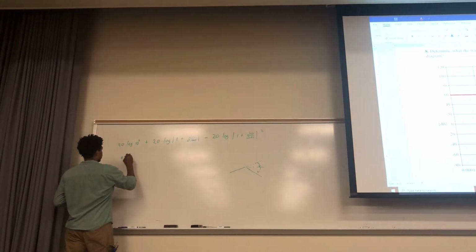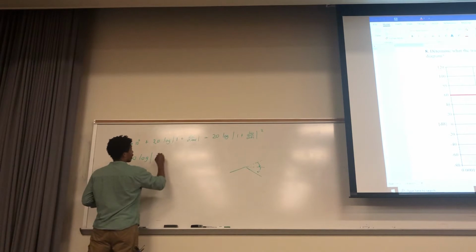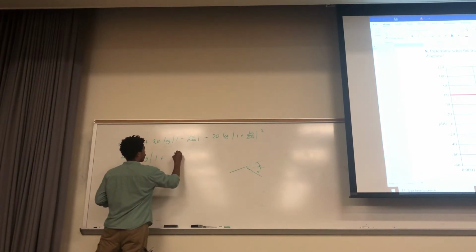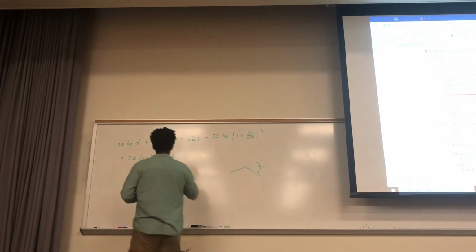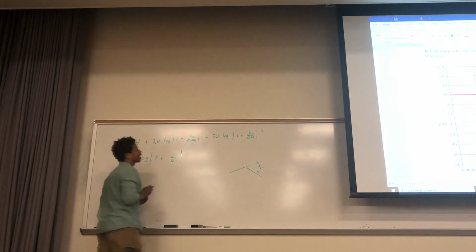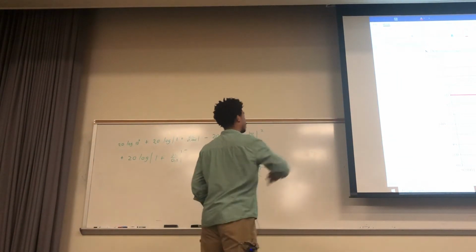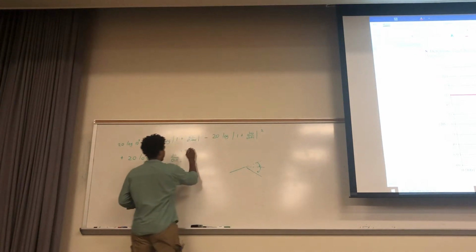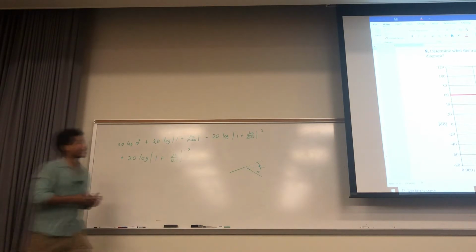So we're going to have plus 20 log 1 plus j omega, and what's the cutoff? 0.1. And this right here, 1, 2, 3, it looks like we did 3 orders down, right?